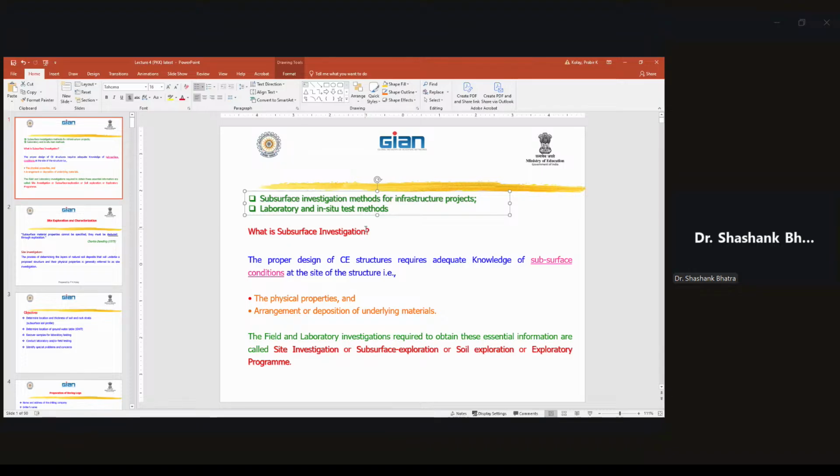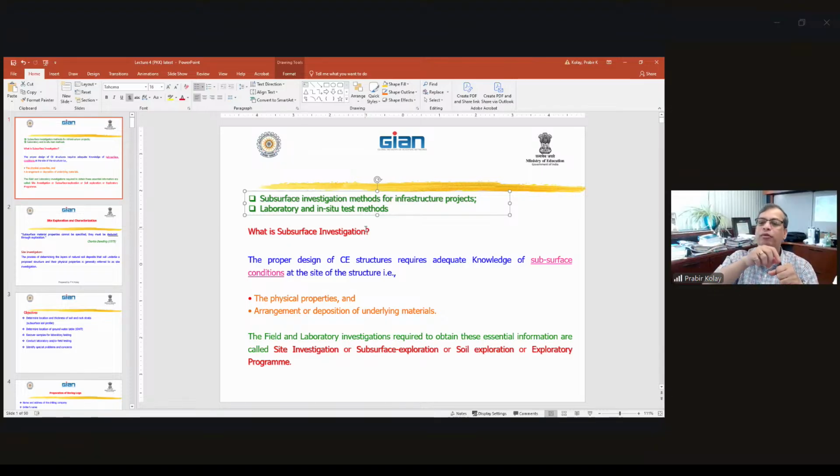I just mentioned what the different methods are. Most of the cases we use one geophone and hammer it, and there are several geophones. The wave will travel, right? It goes to one layer, then the next layer, and then gets received. Most of the time, from the travel time you can easily calculate the shear velocity. If you are using the seismic method, the instrument is a little bit different, and the most important thing is you need to really know how to interpret the data.